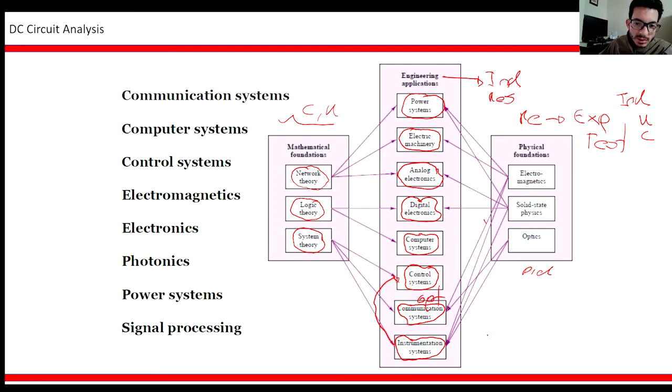The difference is that instrumentation is the hardware, so it's the actual sensor going into an engine, measuring the temperature, the pressure, the flow rate, versus the control system, which is the software, where you write code to control those variables and allow more mass flow of gas and control the threshold temperature, etc. So the software does the controlling, and the hardware is the instrumentation.